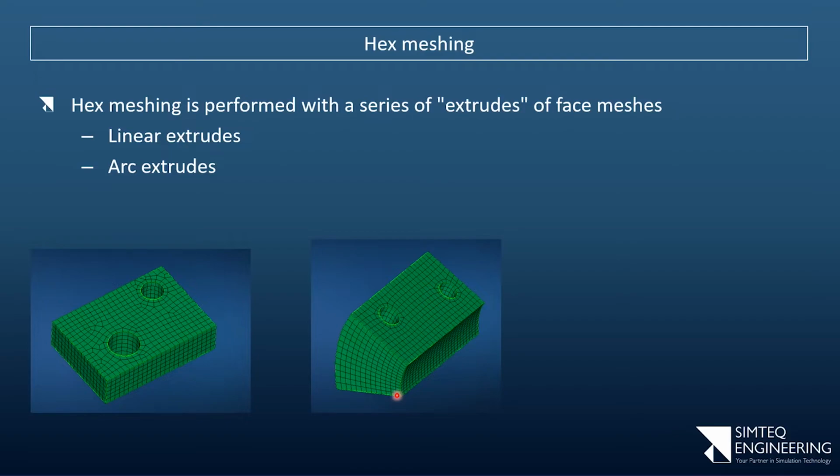And again, this is actually a nice example of some things that go wrong with solid elements or hexes when we extrude, when we do it around some edge. We end up with these bad elements on the inside again, where the aspect ratio starts getting worse. So in this, ideally, we'll want to split off a section there and mesh this face so that it transitions from a fine mesh to a coarser one, so that you can extrude in that direction.